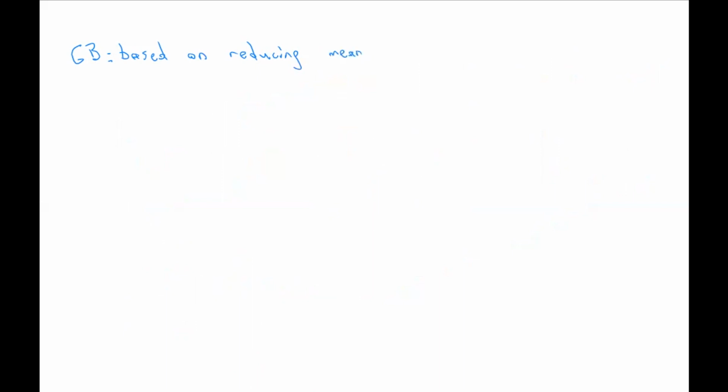That is the main idea, reducing the mean free path of dislocation, which means refining the crystal. It is one of the oldest strengthening methodologies, along with solid solution strengthening. So it is a very old method.